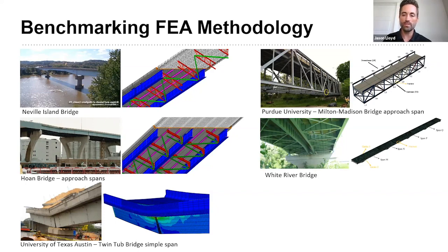The reliability principles utilized in the development of loading combinations described in the AASHTO LRFD bridge design specifications, as well as the AASHTO manual for bridge evaluation, were used to calculate the loading combinations applicable to nonlinear FEA for the sudden failure of a primary steel tension member, and for extended period of service between the member failure and its discovery. So performance benchmarks considering strength, stability, and serviceability of the faulted structure were compiled to set minimum performance requirements for typical steel bridges after the failure of a tension member.